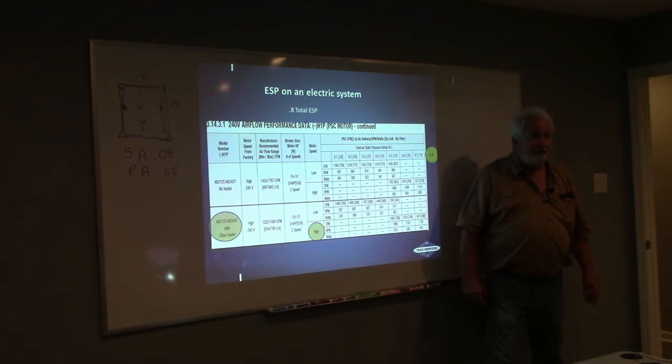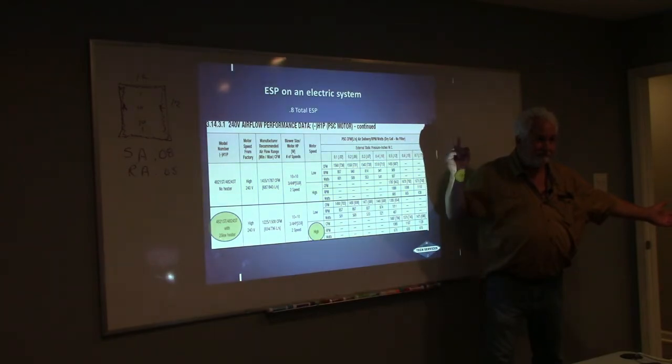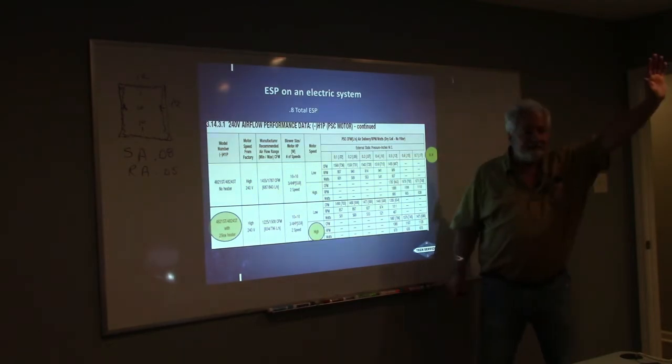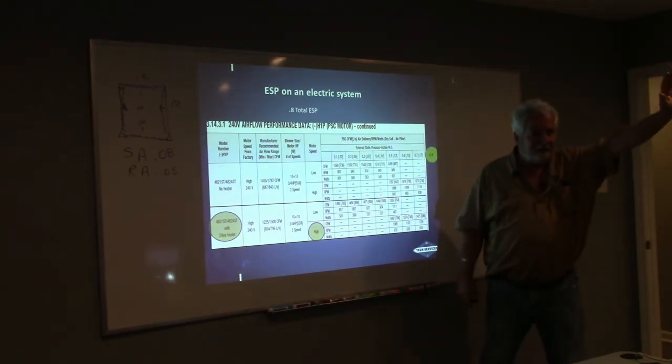You go out there and you say the compressor is gone. What's running inside? Blower. It's back on again. It cooled down, it came back on again. What's not running outside is the blown compressor. You're pissed off because you just put this thing in 2 months ago. Where's the problem? You guys with me? We've got to be checking the external static. This doesn't get it. Cool?